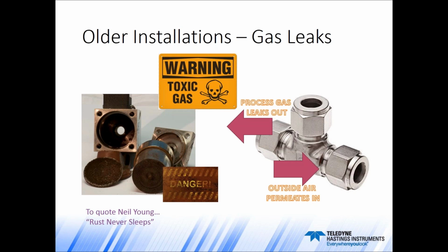What we recommend is customers immediately block the inlet and the outlet of the flow controller, so capping the inlet feeding and the outlet feeding, upstream, downstream feedings of the flow controller. Double seal them if you have that capability. If not, Ziploc bags are doing a great job. Ship it to a service center that can immediately perform decontamination and cleaning of the device, so we can actually stop that rust right in its tracks and bring the MFC back to its original capabilities. This is what we do in service. We're going next.